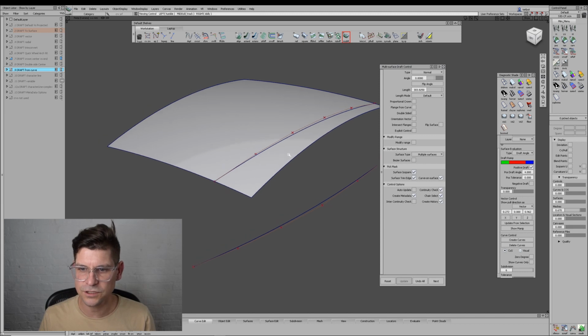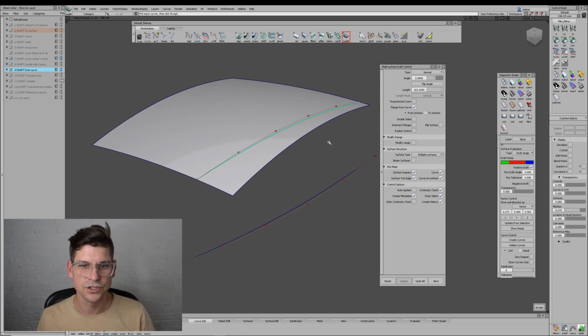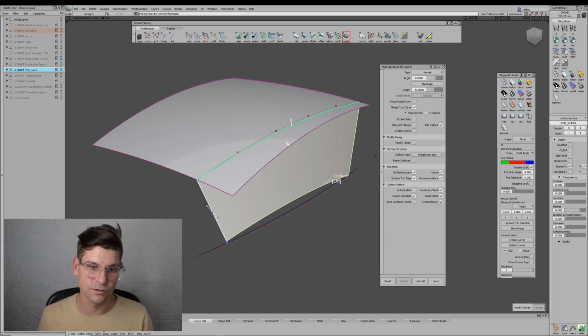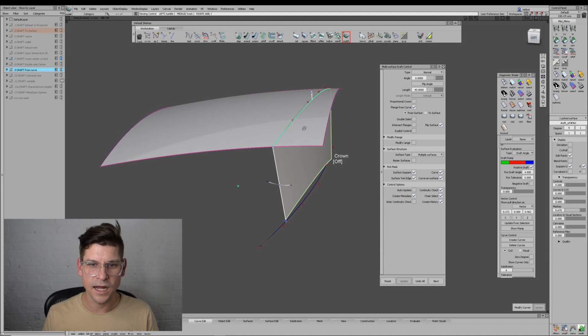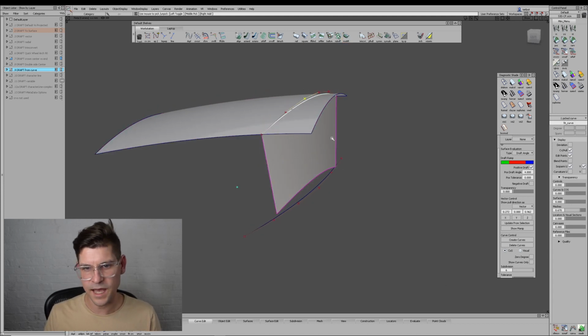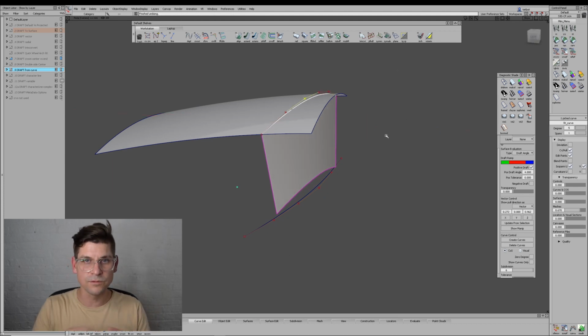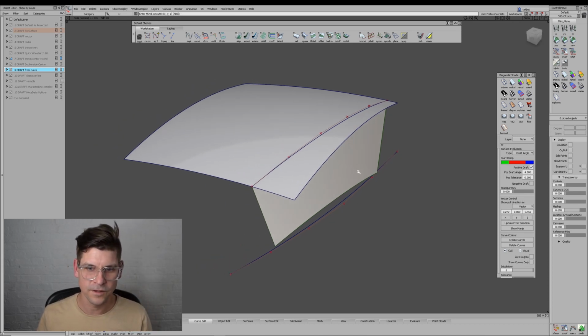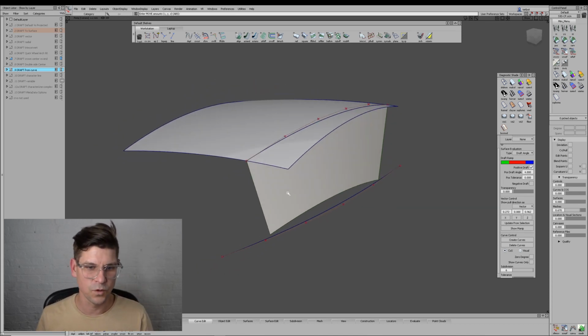But if you just switch or turn on flange from curve, from surface, what I can do is choose a curve, hit accept, choose our surface, and it's going to use that surface as the normal information. So we're building off of the curve onto the surface, and now I'll just move this wherever I want. You can see everything updating, but we would probably want to keep that right on the surface. So that's draft from a curve using another surface's normals.